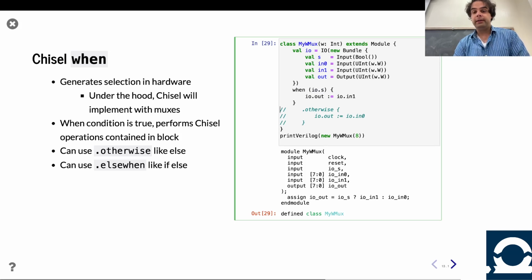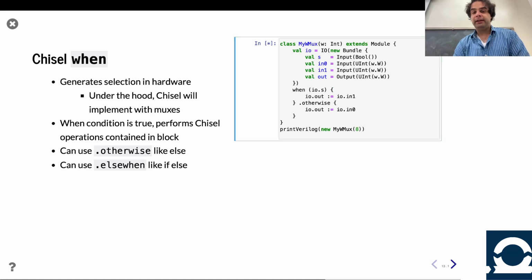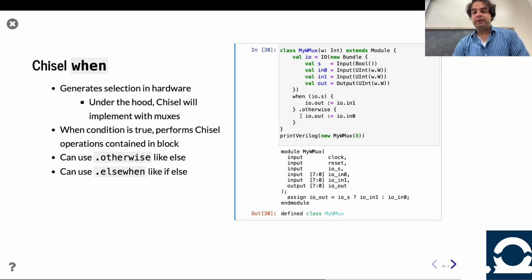Cool. Okay, let's go ahead and restore things real quick. One other interesting aside from a language point of view, people often comment that this dot here is confusing. Why is that there? That's one of those wrinkles from Chisel not being a proper language, but instead being embedded in Scala. It actually turns out that this is a function call. There's some arguments here. This is another kind of argument. This is a following function call. So actually, in Scala, you can remove periods from function calls, and it'll do the right thing.